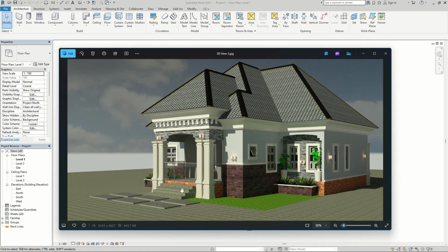When we're talking about the level, because this is the difficult starting point for beginners, we're talking about the base points that you separate your building to actually bring the building to a connection stage. Now, if I click level 1 and I make the base of my assumed ground in this design as level 1, it means I will be working directly on level 1.